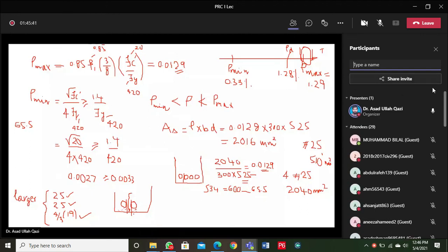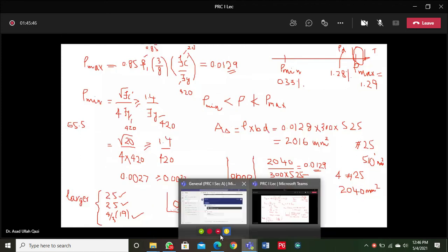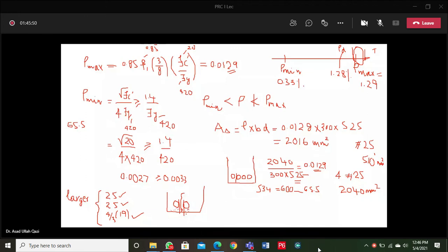Once you open the formwork, you will find that in the cover concrete, quality is compromised because the coarsest particle was unable to flow through the gap. So there is a recommendation that 1.33 times the coarsest aggregate particle should be the clearance available between the bars.